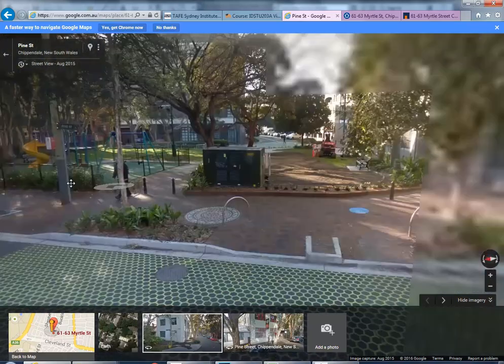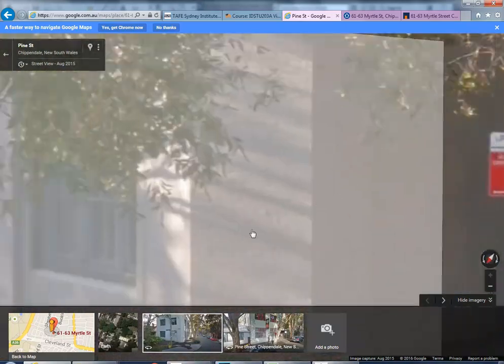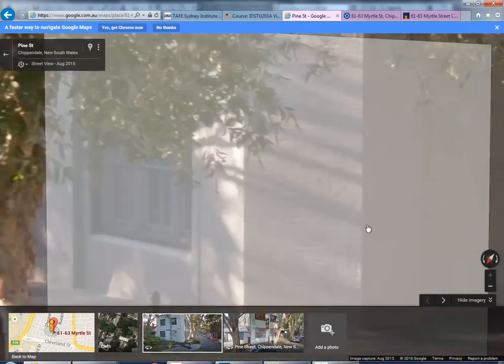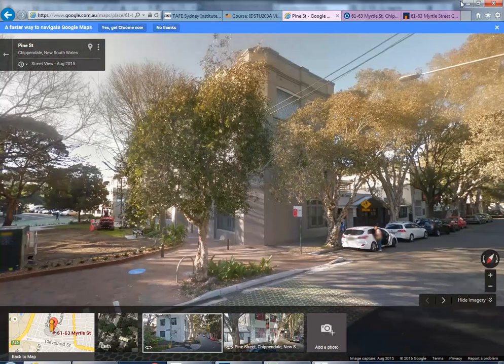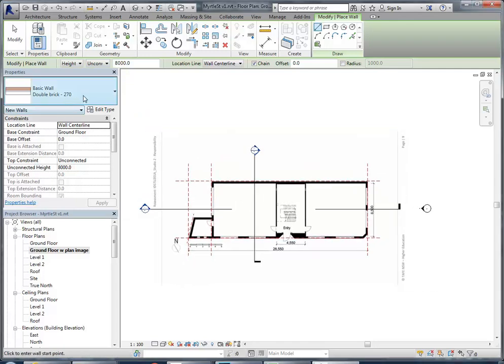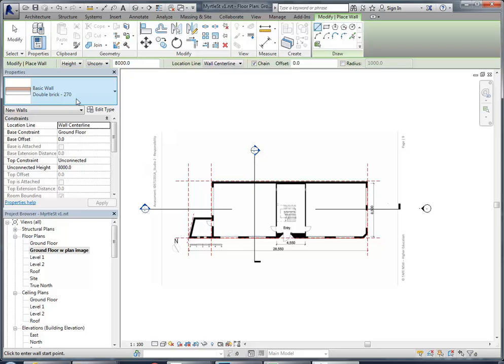Okay, so it's brickwork, and it's not old enough to be solid brickwork, so that would be cavity brickwork. And so that means it would be a 270 wall with render either side, except actually one side isn't rendered, but we're going to say it is. So that means it's probably 290, like I was saying.